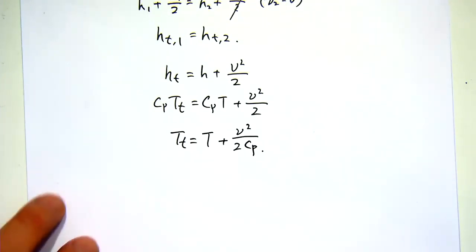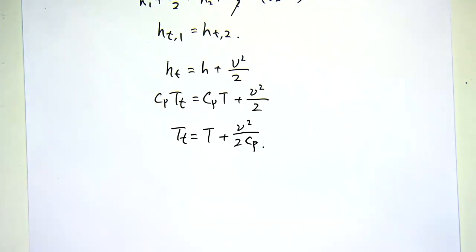And if you're dealing with ideal gases, from the start state to the end state, this process is isentropic, right? Then you can apply the isentropic law to this process to figure out the stagnation pressure.